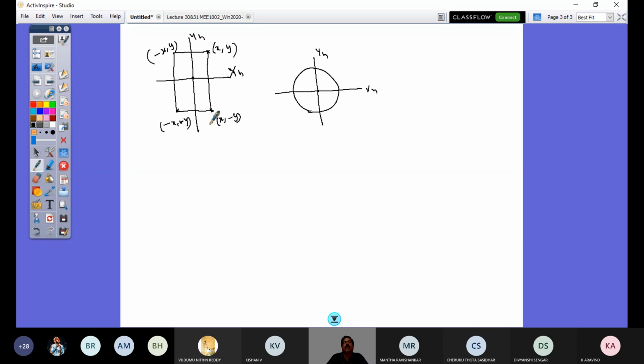If I take corner points, I have it like that. So this product here is positive, this is positive, whereas the product of coordinates here and here, you look at, it is going to be minus x, this is minus and this is minus. And the total sum of all these products is 0. That is why you have product of inertia 0 about the centroidal axis. And product of inertia 0 about an axis set, that axis set is called the principal axis.